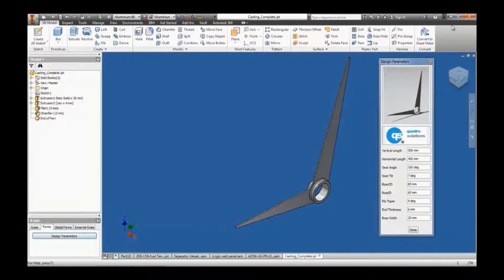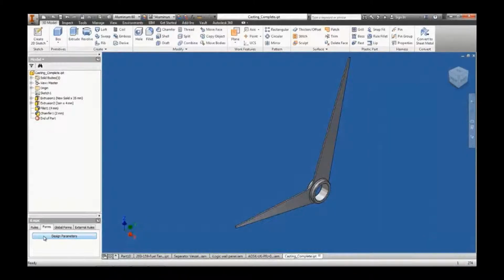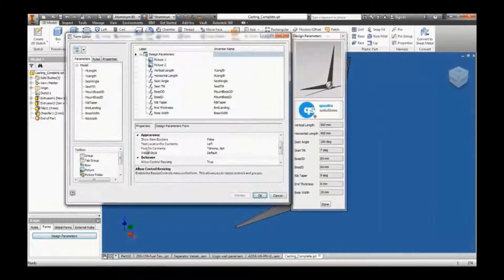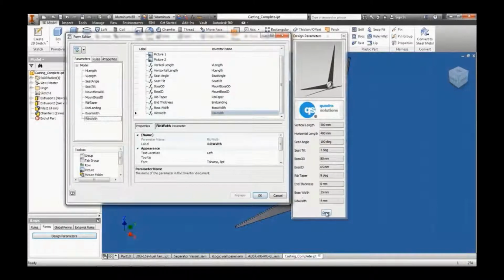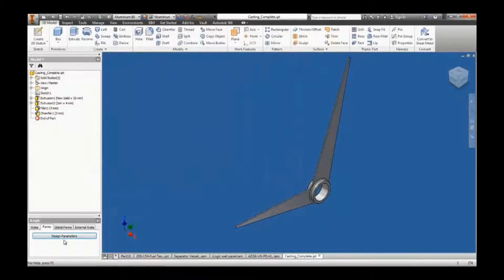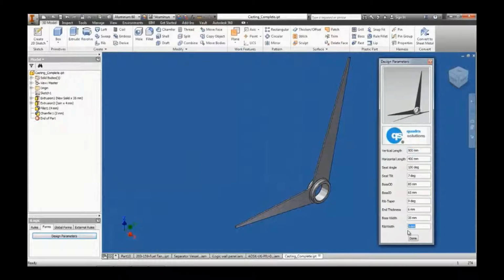The benefit of iLogic though is if you need to change that form, it's very, very simple. You don't need to program it, you don't need to recompile it. All we need to do is edit the form, find the element that we've missed, drag and drop, we see it gets added to the list, and that's it, job done. It's instant, so we can make that 10 mil for example, and we can see that the file updates. It's that quick, it's that easy.